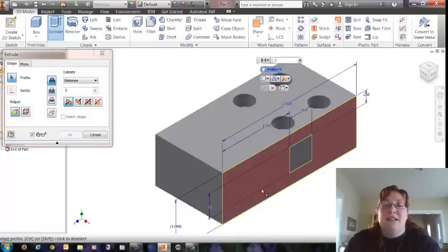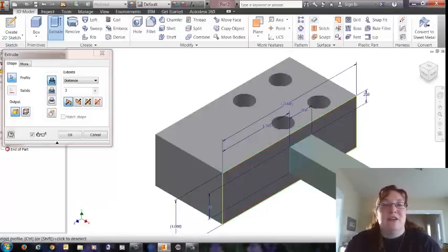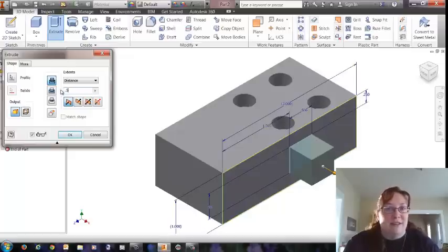I'm going to click on one of these lines, and I'm going to click on extrude. Now I have to tell it what I'm extruding. This is extremely important because I often have people go over here and make all sorts of changes, and then they don't realize why they can't click on anything, or they end up extruding the wrong thing.